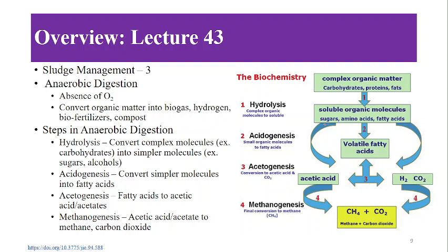Here the acidogenic bacteria convert these simpler molecules into fatty acids. And then these fatty acids are converted into acetic acids or acetates. And then the methanogenic bacteria act on these species of acetic acids or acetates to form carbon dioxide and methane.